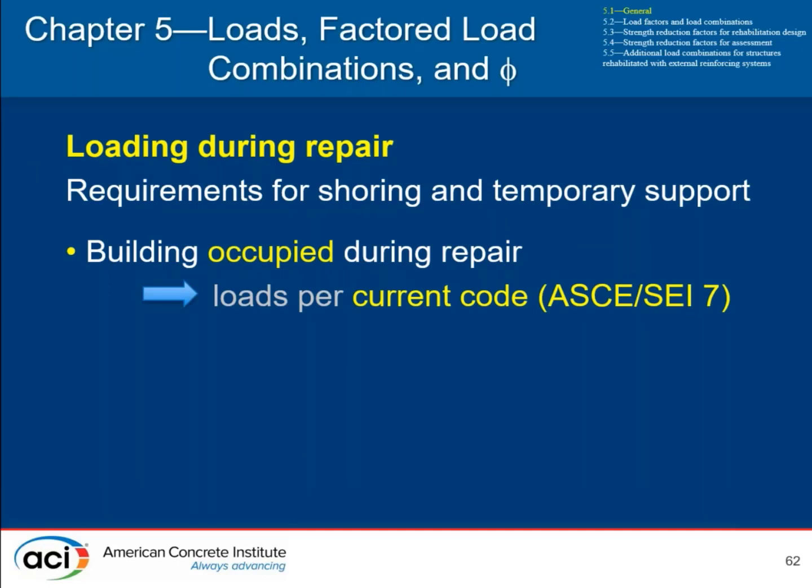What loading should you be using during repair? Well, you need to think about that loading because you're going to be using that to define the shoring and temporary support requirements. If the work area is going to be occupied during the repair, then the loads are per the current building code, ASCE/SEI 7.